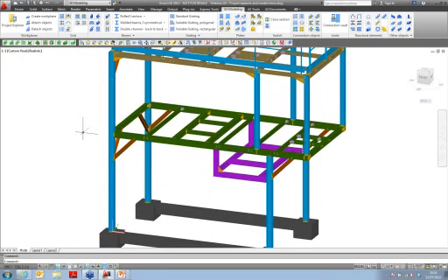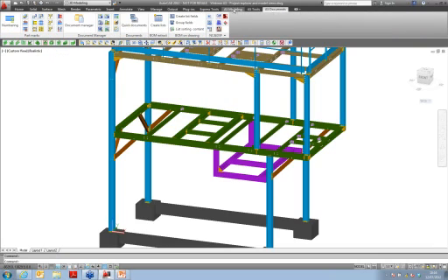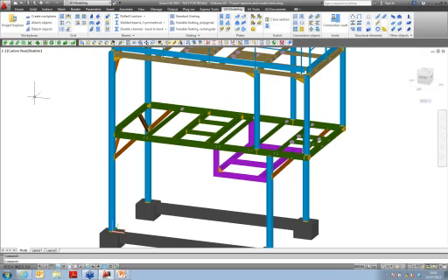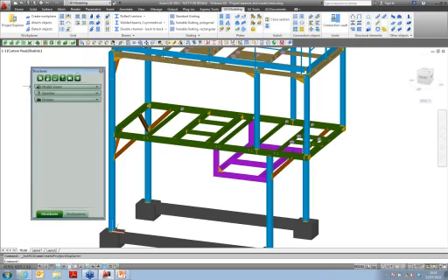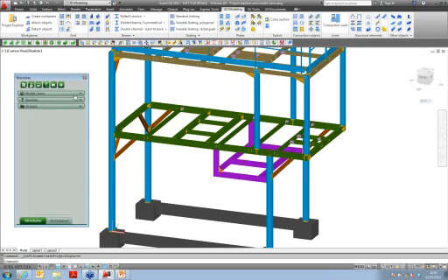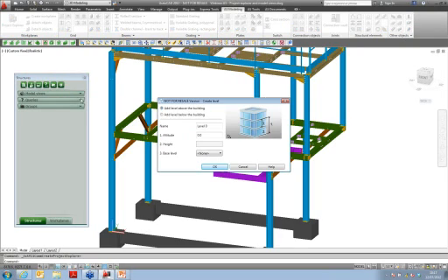So for the Project Explorer, it's very easy. Here you have the different ribbons with Advanced Steel ribbons, modeling one, tools, and documents. And with the Advanced Steel modeling ribbon, it's easy to start and to open the Project Explorer. So my Project Explorer here is empty, and what I'm going to show you during this webinar is how to create specific model views, user-defined queries, and create your own groups. Okay, so let's start by creating a first level. I want to create a level which is, for example, at level 0.